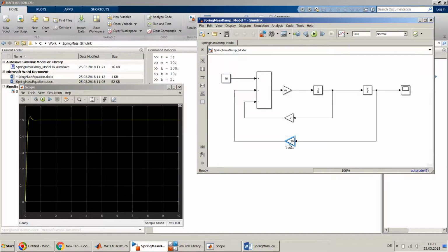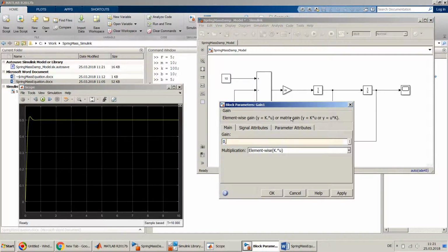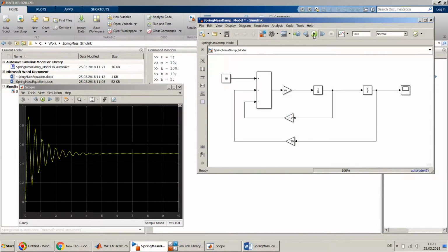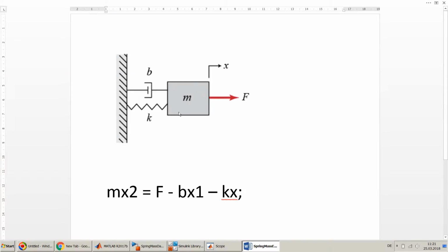Okay, so this needs to be high and this needs to be further low. Yes, this is what I wanted. I wanted this kind of waves, and if you see, it's getting settled somewhere around 0.5 here, and that's because there is a constant force being applied to our mass spring damper system. So since a force is being applied, x of around 0.5 is the stable or equilibrium position.